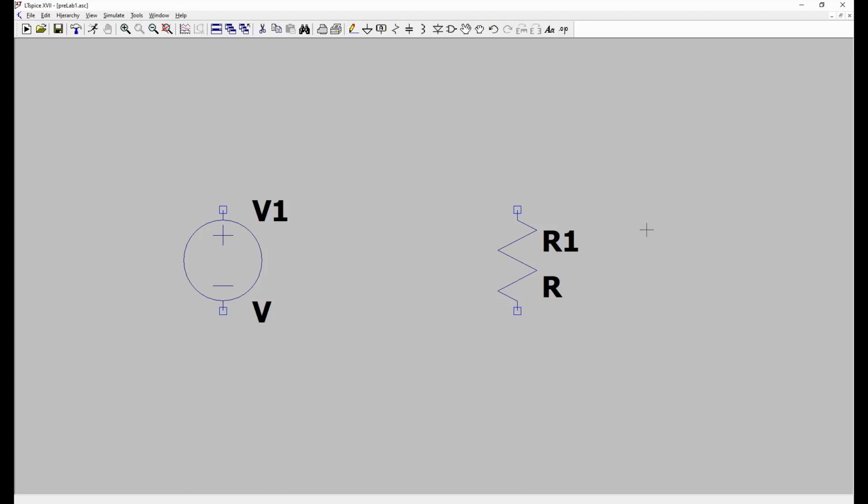Right click on the voltage source, and you can tell it what the voltage is. For now we're just doing a static analysis of constant values. So this value is going to be, for us, 5 volts. The resistor, let's make it easy, and we'll right click on the resistor and make it 1000 ohms, or you can just simply type 1K. LTSpice understands that K means 1000.